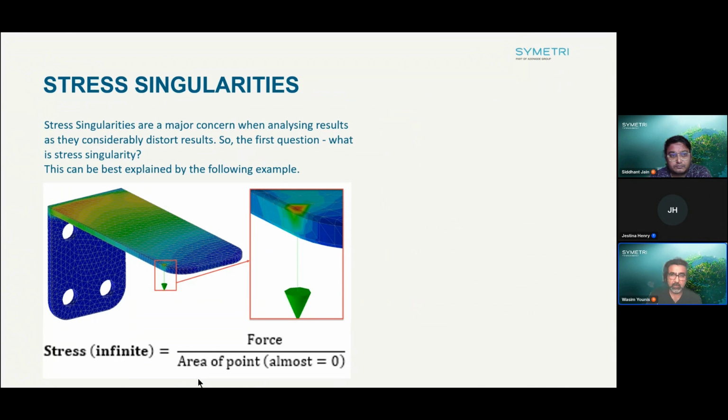And I think one of the tips I would suggest is never ever apply a load on a point or a small edge. If you need to apply a load on an area of a face, then we suggest that you create a split face using the split command. Split command is probably the most popular command for Nastran. So that's what I would suggest. But that one is not the most popular stress singularity when we do support calls.